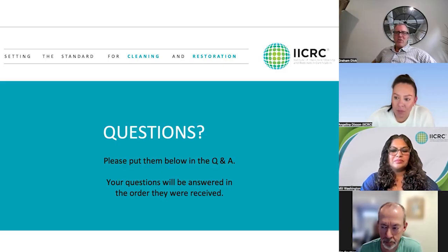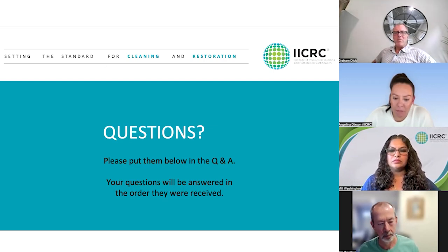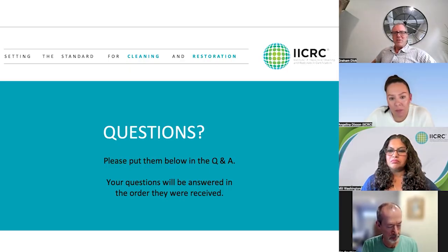Ideally, your vacuum would be a built-in, and the exhaust doesn't exhaust inside your garage, but it exhausts outside, so it doesn't re-entrain into the house. When you exhaust into a garage, that re-entrains quickly into the house. So any fine particulate comes back into the house very quickly. The way I explain that is if someone goes and lights up a cigar in your garage, how quickly do you smell it in the far reaches of your house? Almost instantly. So it is with the vacuum exhaust. Anything that's coming out of that exhaust is back in your house almost instantly. So that's how built-ins work.